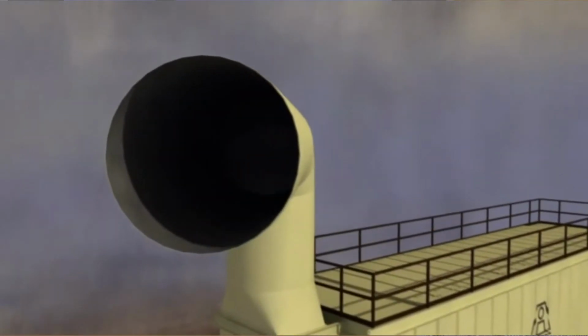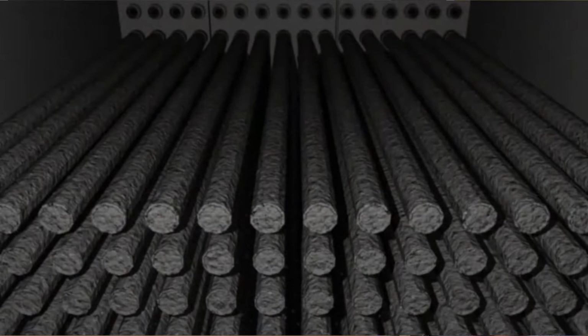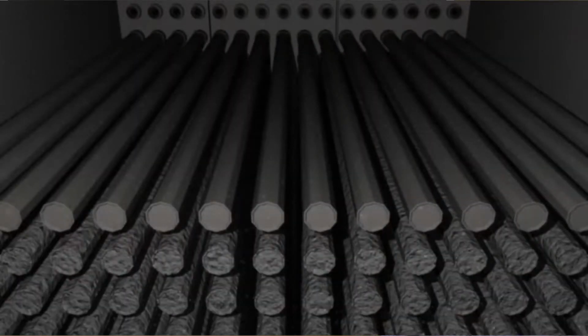As you pull the dust into the stack, it's going to fall down through. Here's your high velocity air. It hits the louvers, your minus 100s will fall, your minus 200s will move on into the baghouse. As the dust moves into the baghouse, it will cling to the bag. This is your dirty air side, and it will push the clean air up through the top to the clean air side. Here you see the blow pipes pulsing down into the bags, and what they're doing is shocking that bag and knocking that dust off. So here's an illustration to show that.